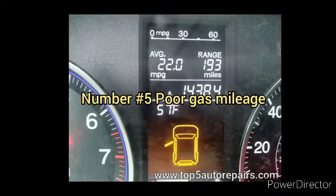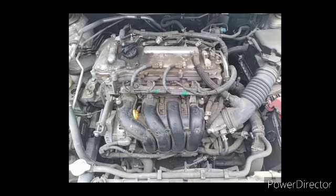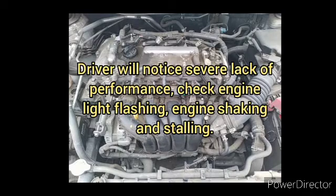Number 5. Poor gas mileage. Again, when the engine performance suffers, gas mileage will also suffer. The driver will notice decreased miles per gallon. Number 6. Misfire. Although it is rare for an engine to misfire due to a blocked catalytic converter, it can happen. The driver will notice severe lack of performance, check engine light flashing, engine shaking, and stalling.